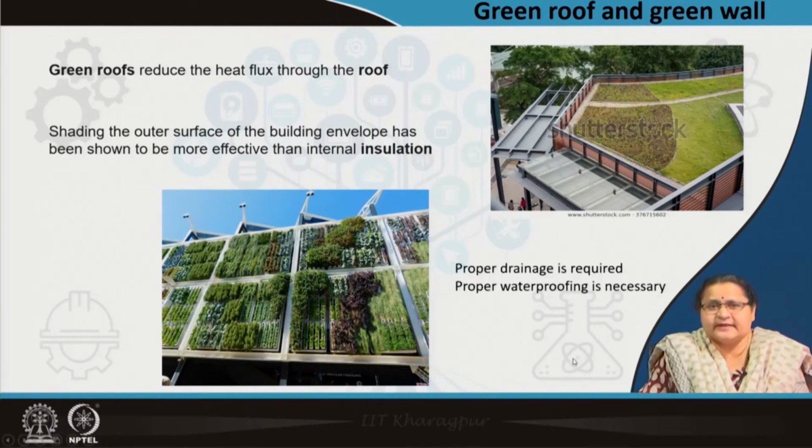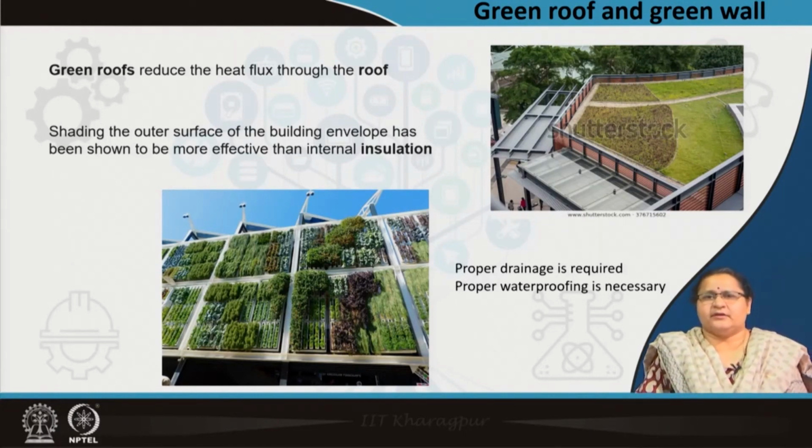But in both cases, one has to be very careful about the drainage part, otherwise it will lead to damp. Already we have discussed that at length. So, your roof will become a leaky one, it will finally disturb the structural roof and finally it may ruin. Same with the case of the wall, on the wall surfaces you have to be very careful about the roots etc. and also about water logging.